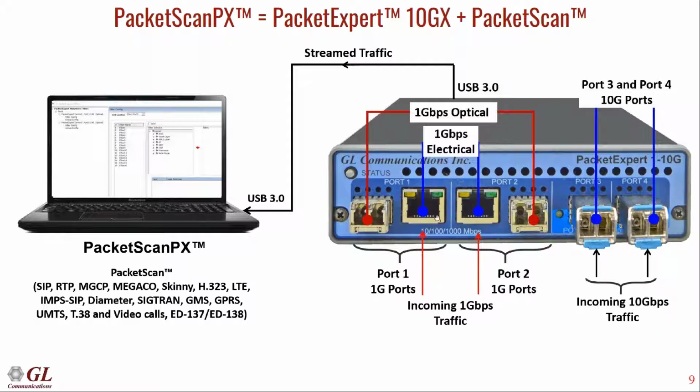As mentioned earlier, there is a lot of flexibility in the ports. So we support both electrical as well as optical ports. Here port 1 and port 2 are dual interface ports, so they have both RJ45 and SFP interfaces. The user can select the mode, whether to operate in 1G electrical or optical mode, from the software. And on port 3 and port 4, they are SFP+ based ports, so you can plug in the appropriate SFP, either optical SFP or electrical SFP there.